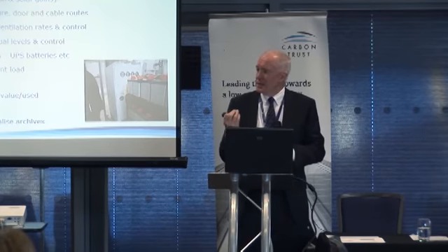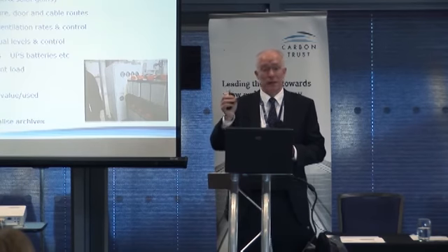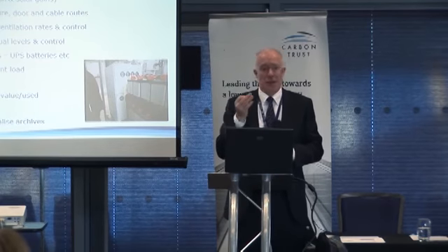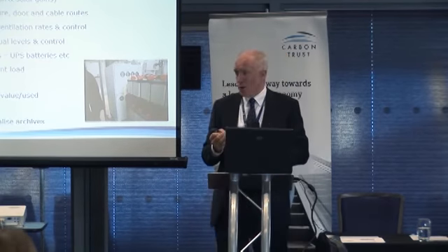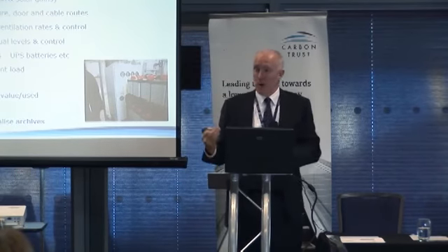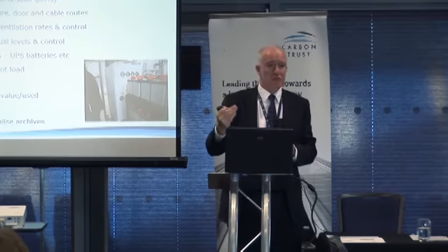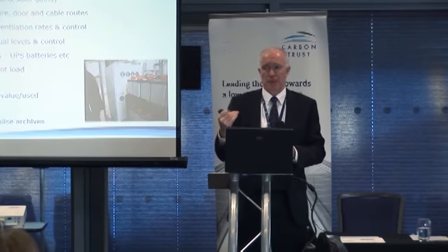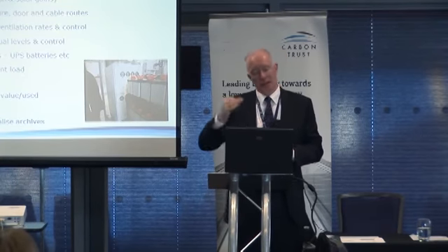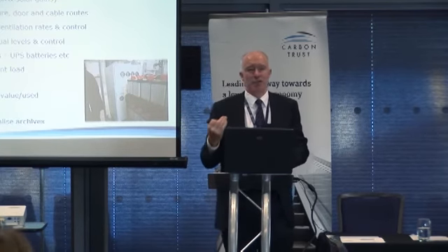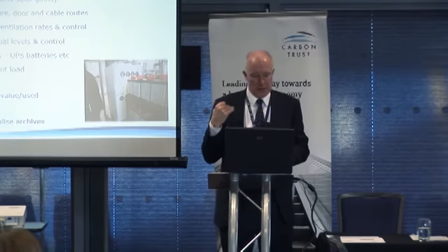People need quite high lighting levels when they are doing work on the IT equipment. When they're putting all the cabling in, they're looking at little numbers and little grommets on the wires and making sure they plug them in right. They will need quite high lighting levels for that detailed work. So perhaps high lighting levels when they're working actively in there, and a very appropriate lower level of lighting, perhaps 150 lux, which is perhaps a quarter of what you normally have for that computer room when it's just general occupancy, and get it switched off when people aren't there. Get your batteries, any heat gain that's not necessary, out of the air-conditioned environment.